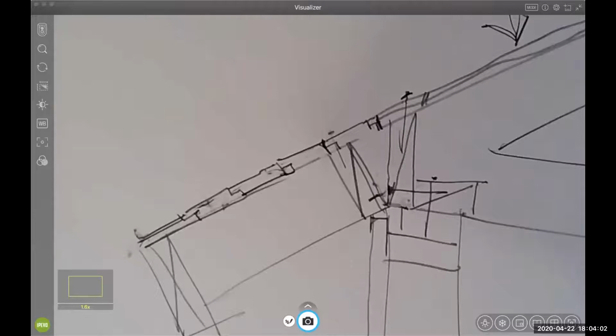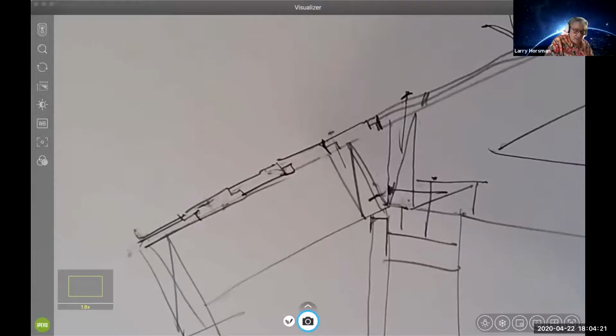Larry, quick question. Yes. On that block, the 2x6 I think it is, instead of the block on the top plate, could you use an A35? Would that do the same, and would that pass the inspection? Yeah, you can. You can use an A35 here.